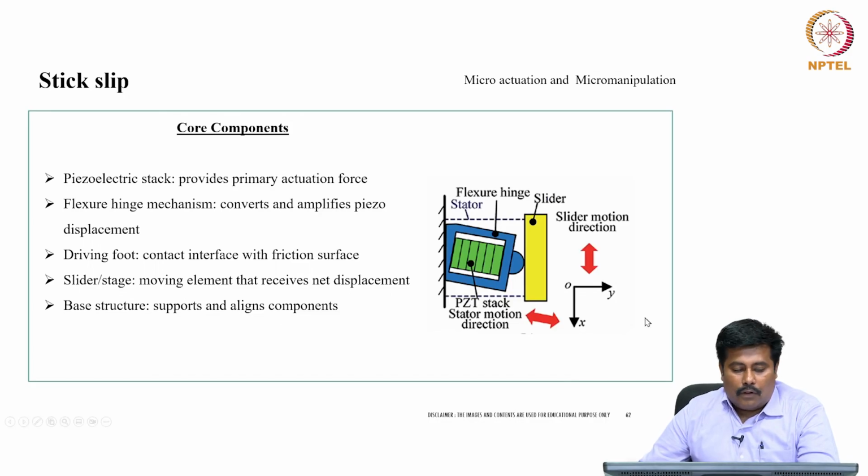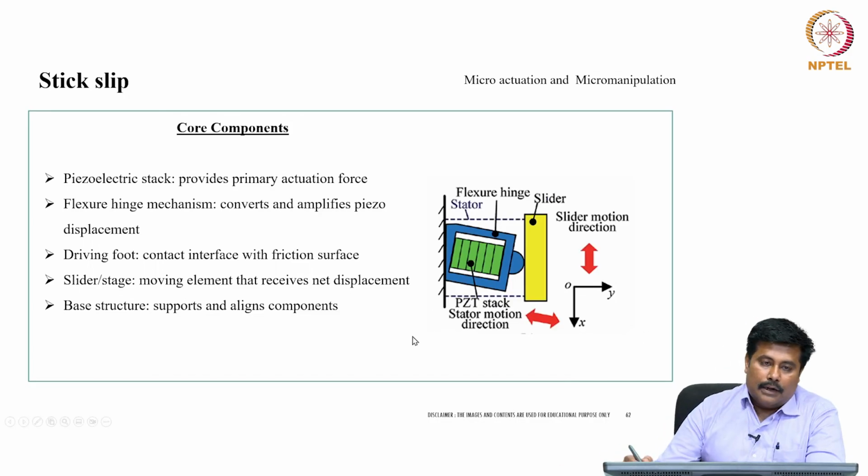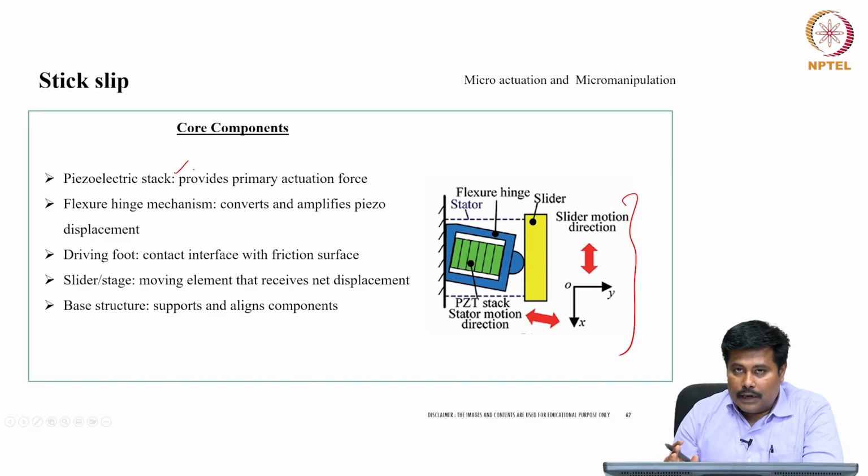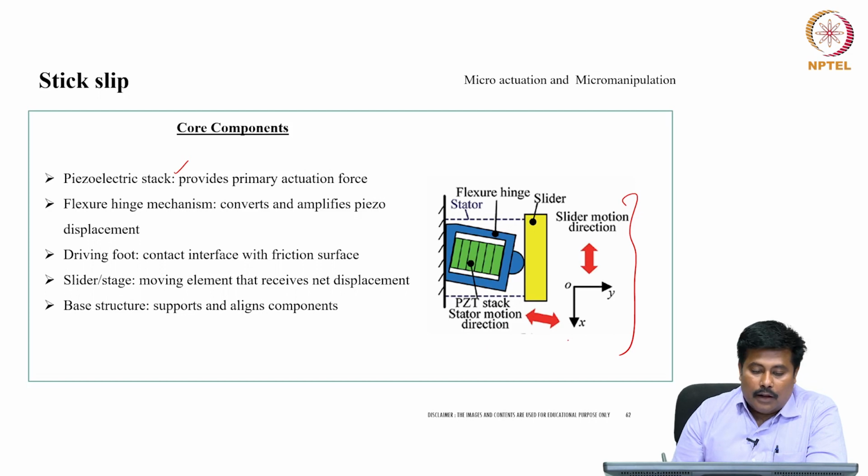Some of the core components of this particular stick slip mechanism are as follows. One is called the piezoelectric stack, which provides the primary actuation force to the system. So this is the overall figure for the stick slip mechanism, where there is a piezoelectric stack with the stator motor and direction, a flexure hinge stator, a driving foot, a slider stage, and a base structure.